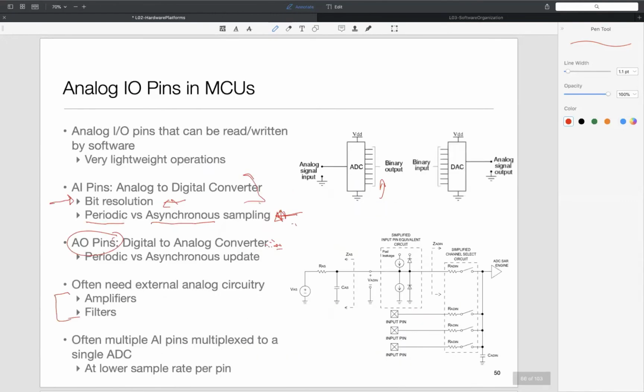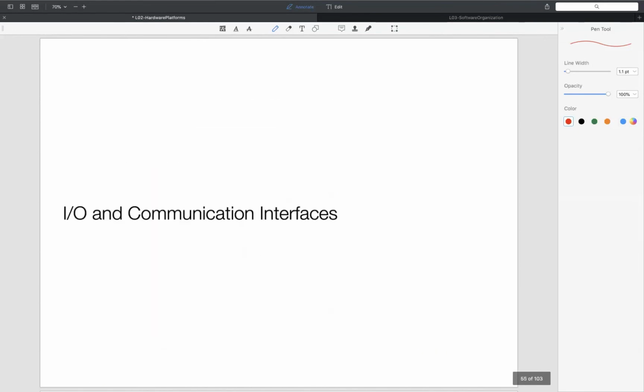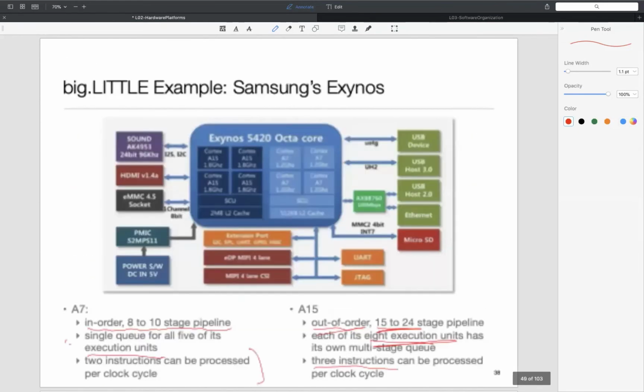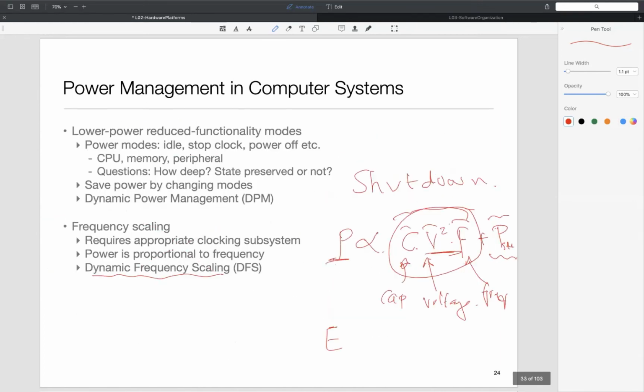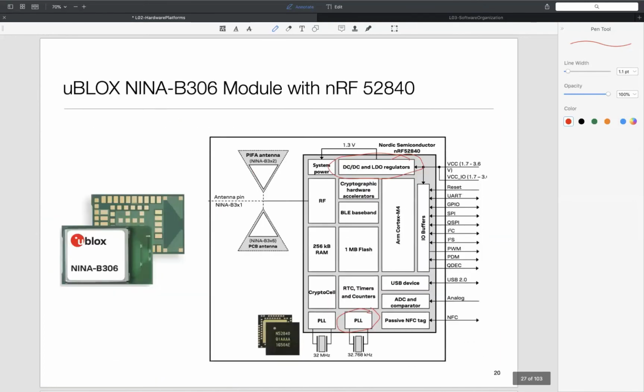In fact, if I were to go back to where I had, I have to go back a lot, but let me just do that. Okay, here. If you notice, this processor has a PWM signal coming out directly. That means it has some hardware in there to which I can simply tell what value I want to be output, and it generates a PWM signal with the desired waveform.